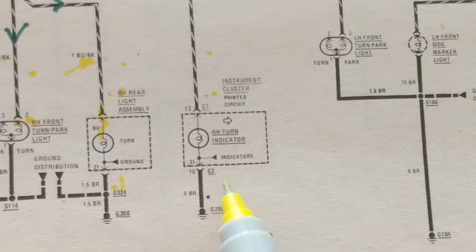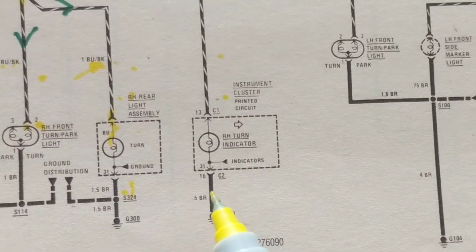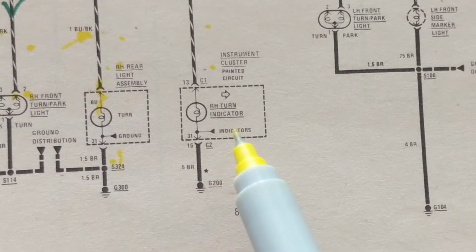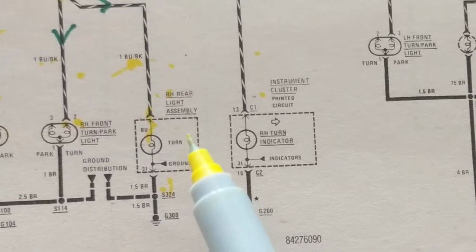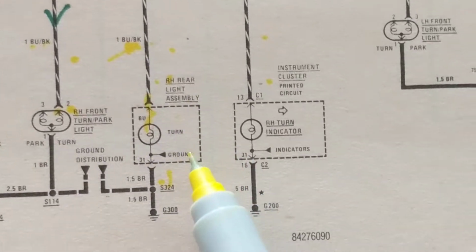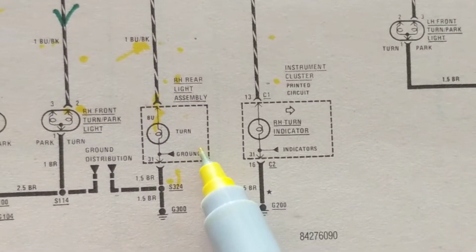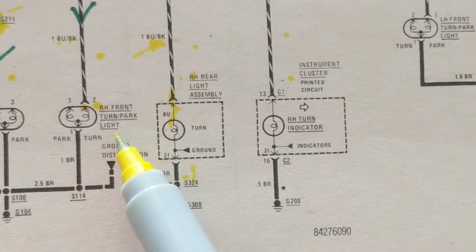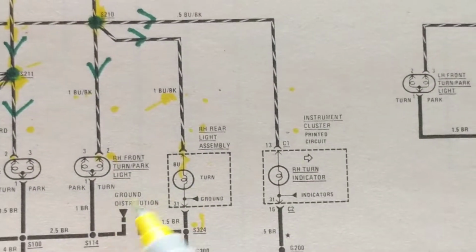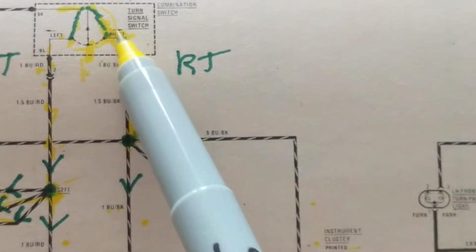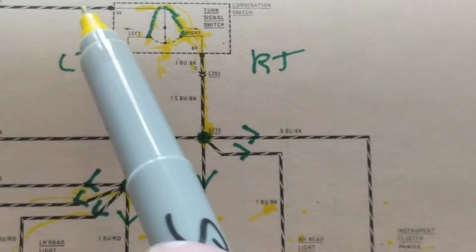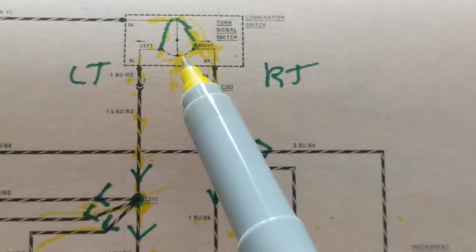Let's say the right turn signal doesn't work. I go to my car in the morning, I turn on the lights, and the right turn signal on the dashboard doesn't turn on. The rear doesn't turn on the right. And the parking lights on the front don't turn on. That tells me all these are common. That tells me maybe again the switch doesn't work, or somewhere the switch doesn't work.